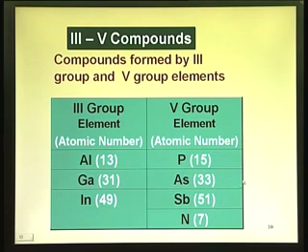Then you can expect here combination of gallium and phosphorus, gallium phosphide could be indirect, because the atomic numbers of both are small, and the other two, gallium arsenide, gallium antimonide, could be direct because atomic numbers are high. But for any law, there is some exception. Gallium nitride does not fall into that category somehow. That is a direct band gap semiconductor, though the atomic number is small there.